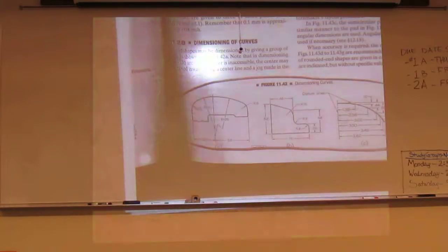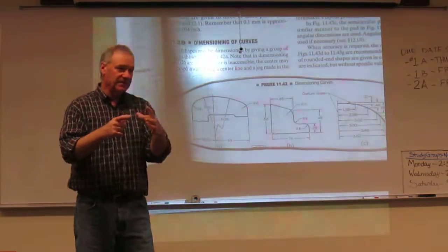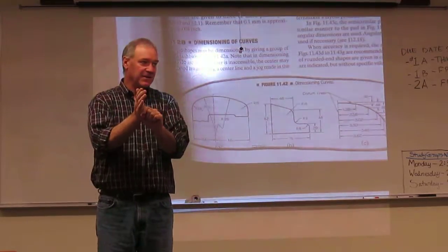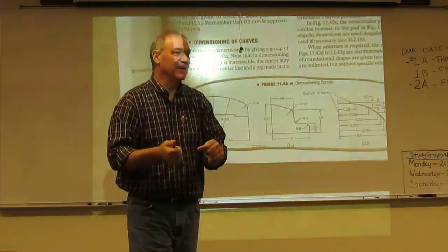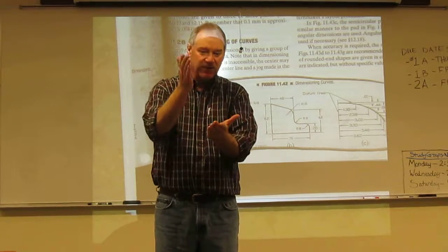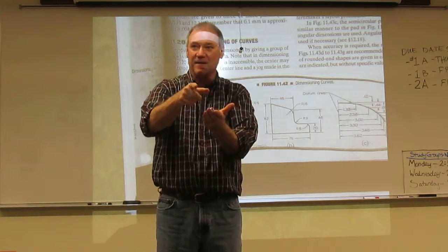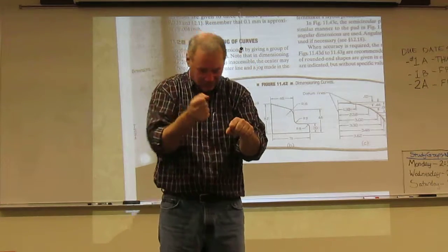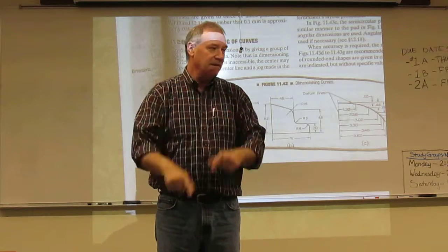I always had a statement that I picture myself when I've got an object and I've dimensioned it, I actually sit down with the drawing once I've printed it and I start looking at each individual line and saying, do I have the information? I picture myself sitting on my little workbench with a chunk of wood and a saw or something, saying I'm going to cut this stuff up. And I look at it and say, okay, how am I going to make that cut? And I start looking through my drawing and say, well, there's the dimension to get to there, there's the dimension to get there. I can locate that, now I can cut it, and I visualize myself grinding or whatever the case. And I go through every single feature on the object.